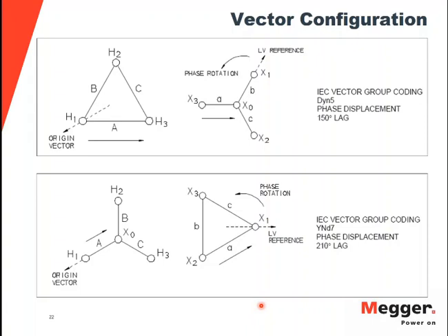Coming back to the question, the 35% of nameplate kVA, as long as your tertiary winding is derated, there is a high probability that you may run into the voltage dependency. And if you run into those, refer to the slide that I mentioned, and you guys will be getting a copy of those. But I have seen that anytime there is a derating of the winding, you may see or run into voltage dependency.